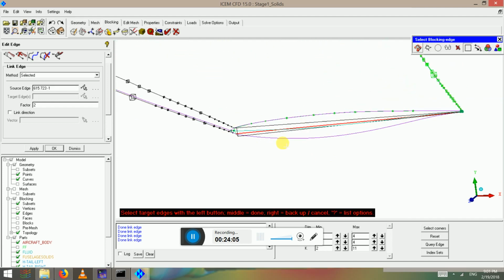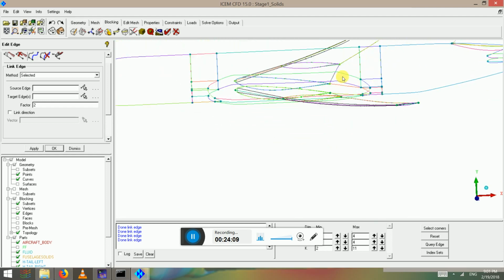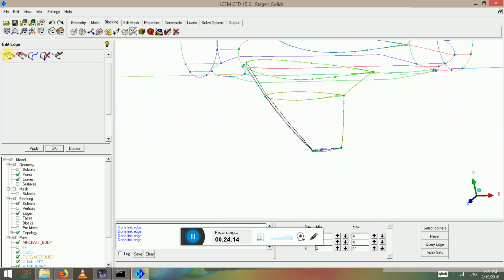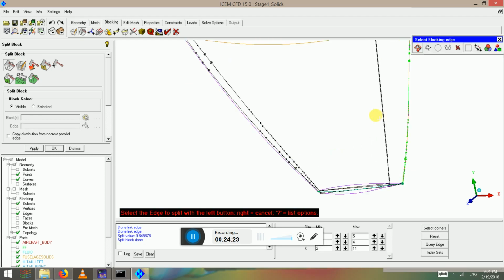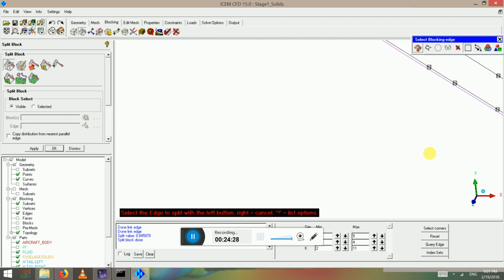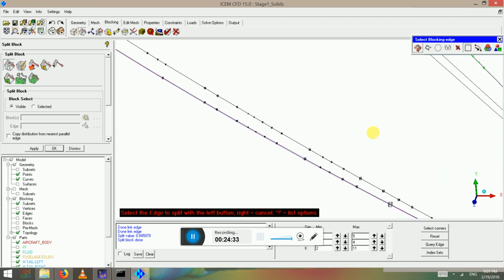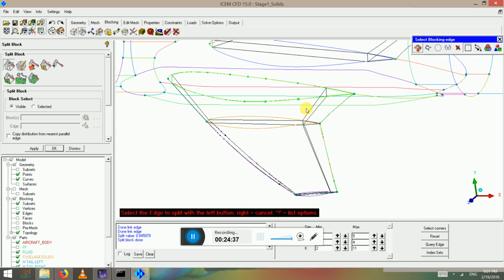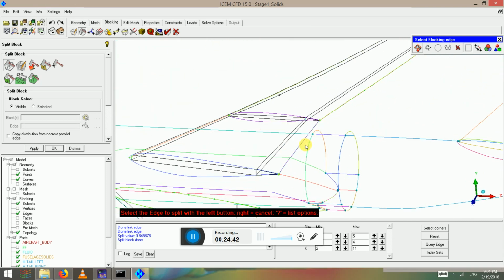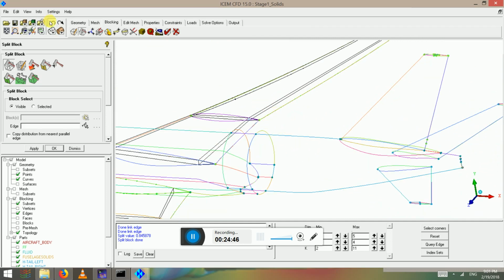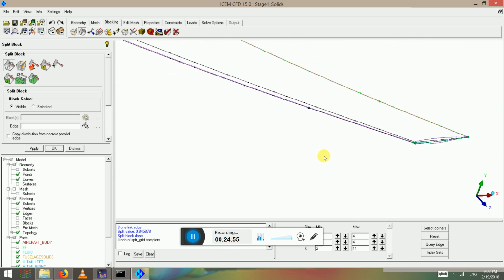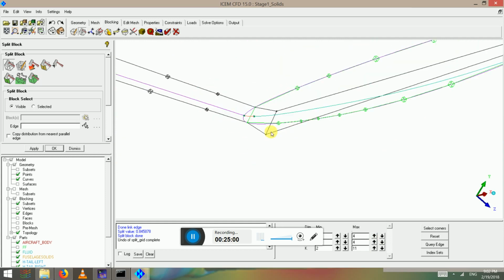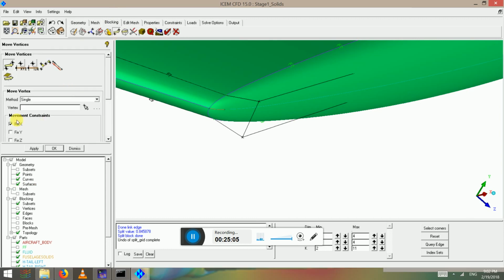Okay, so we've done the wing quite well, I would say, except we need to introduce a split right before the actually, let's ignore it for now. Okay. We can do that later. Let's just try and associate, move these around. So this surface, I want to move these vertices in the X and Y direction until they hit the wing surface. So somewhere here and somewhere here.